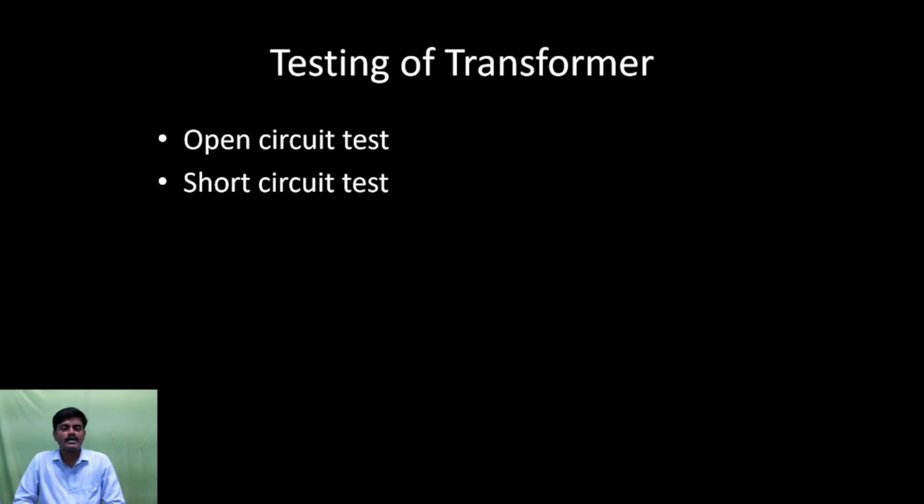Then we should have the testing of the transformer. Suppose I am using the transformer year after year. Then whether the characteristics of the transformer have changed or are maintained, I have to know. For that, testing is very important for any device. So how is the transformer tested? By means of two things: the open circuit test and the short circuit test.